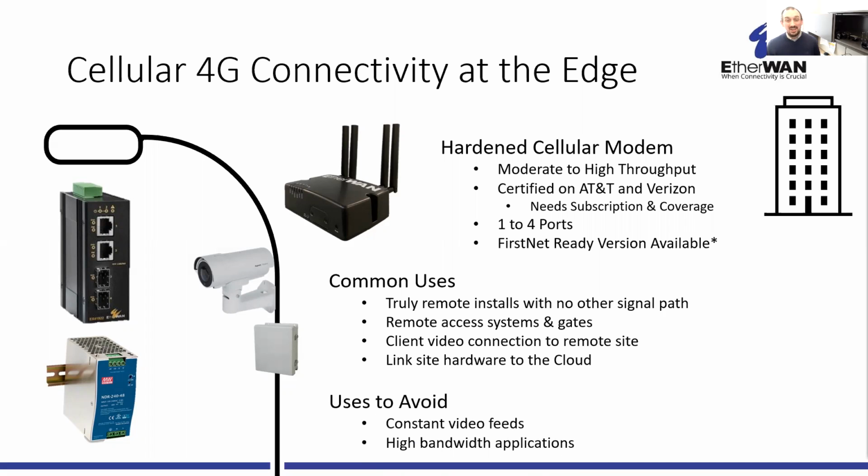So ultimately, those are the kind of gotchas with cellular. It's kind of similar to your normal phone, right? You want to make sure that you're avoiding constant video feeds if you can, because any data that's sent is going to affect whatever service plan you've contracted for the SIM card you're putting in here, as well as really high bandwidth applications. Because ultimately, there is an upload limit for these cellular devices. It's going to depend a bit on signal strength, so it's hard to give you a perfect number that's going to work for each area.